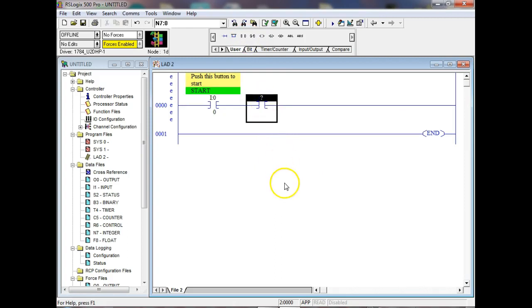I've already used it. And you can use the same address multiple times, guys, but it wouldn't do much sense for me to put the same switch twice, right? So if I'm in a push button, then if it's got the same name, then it would have multiple contacts on it. This is all software, so we can simulate as many contacts as we want to.